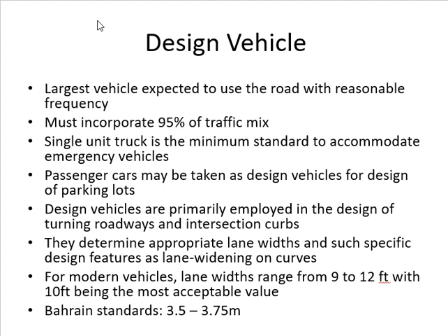What are the things in road design which will be affected by the design vehicle? First of all, if the vehicle is bigger, or if the vehicle is heavier, it will need more space. So the width of the road is according to the design vehicle. Secondly, when you are designing the turnings, whether you are designing a curve or a turning on an intersection, it will depend upon the size of the design vehicle.